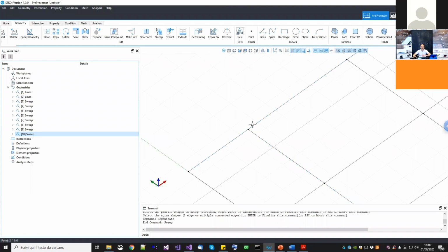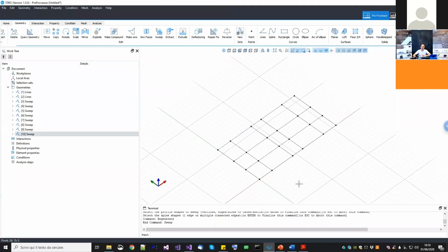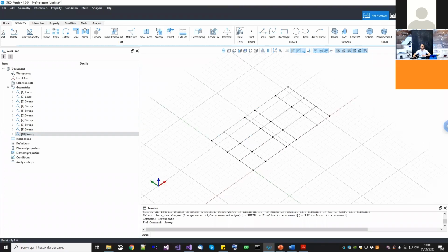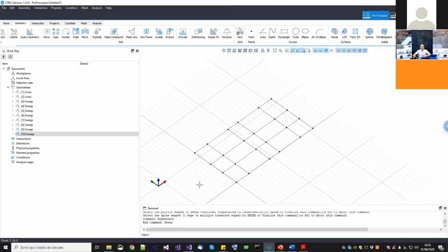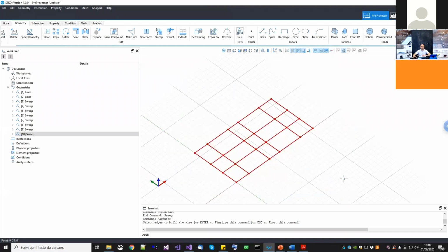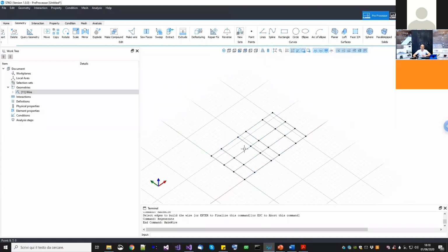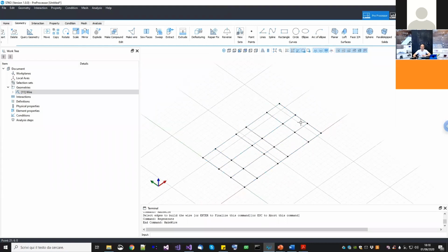So for example, in this case, even if you see a single vertex, these are actually 2 overlapping vertices. So if you want something that is physically connected, you need to use a Boolean operation. Now, in this case, we have all lines, so we can use the make wire. So we select all of them, just like this, right click, and all those lines now are joined into a single polyline, okay? So this one will be the base for our floor.